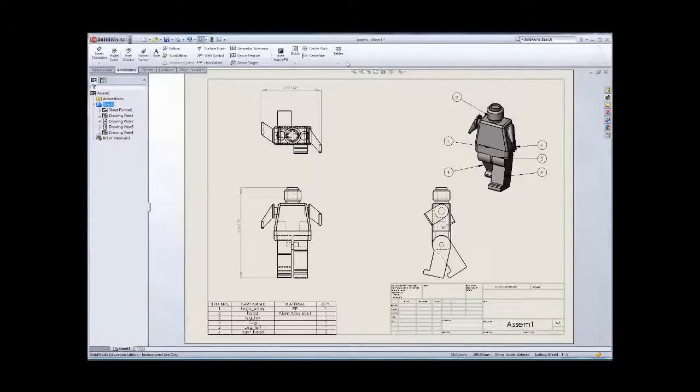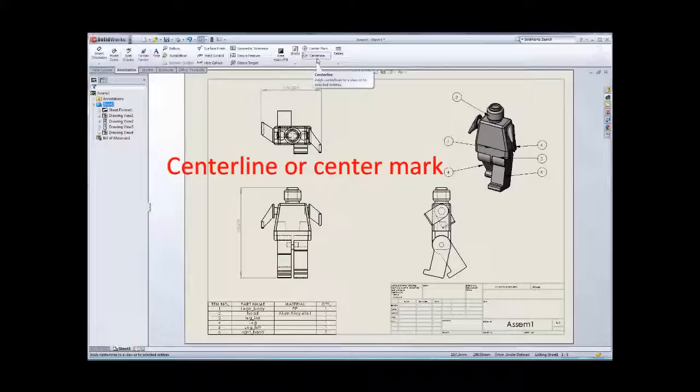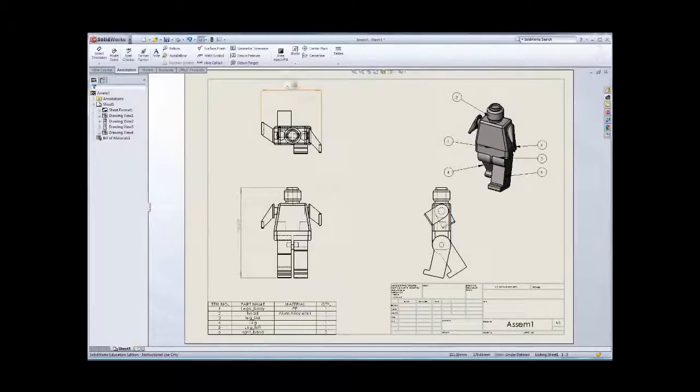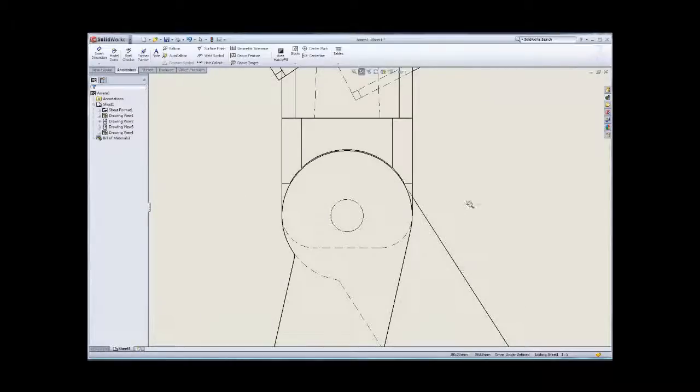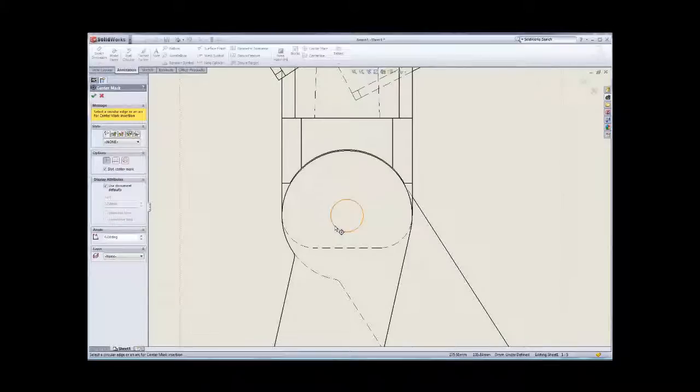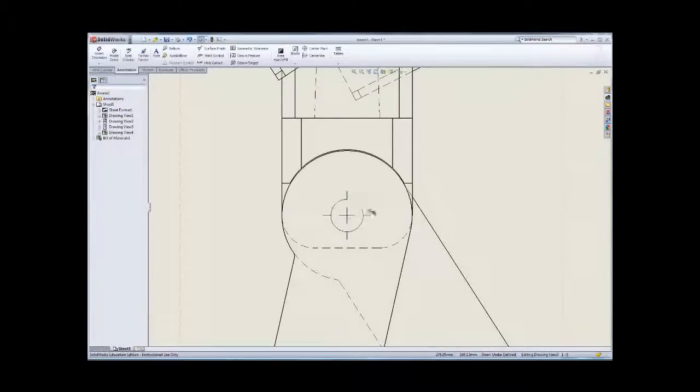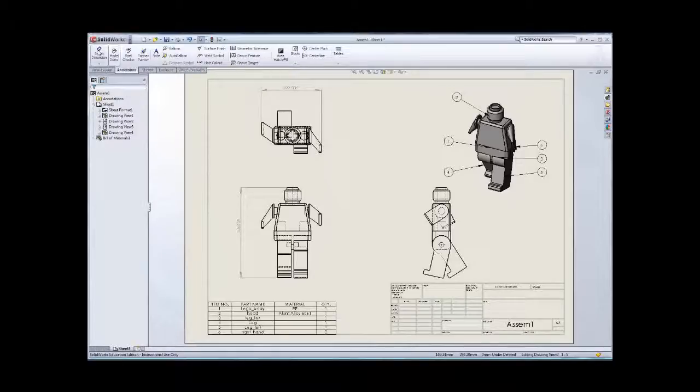because we use the table BOM here, and then if you have the whole table, you can just make it. And then in AutoCAD we cannot do the center line automatically, but you can just click into the center line, because I think we need to make the center line. Center line is the bisect line in the middle, so you can make some center lines in the middle, or you can see we have got the circle, we can have the center mark. You just make the center mark and then click into that circle. You can see it will draw the center mark in the middle. So I think that one is very useful.